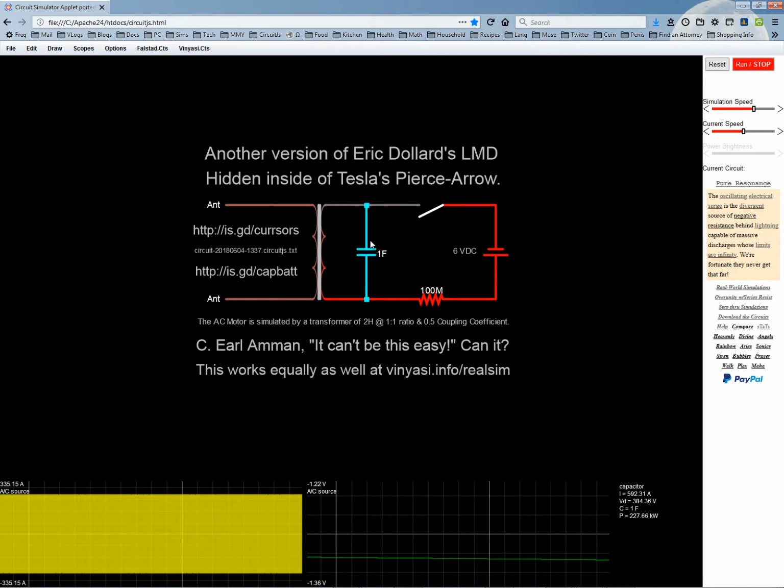But all you have to do is go up and down, and you'll achieve the same effect as if you were raising the capacitance ad infinitum, with no limit imaginable. So these are workaround little tricks, and he invented the darn thing, the variable vacuum tube capacitor, so that he could do that. He could toy with the capacitance and make it go up and down while it was running. And if you try to do this in LTSpice or Microcap, forget it, because it's not a dynamic simulator. Only in Paul Falstad's simulator can you do this.